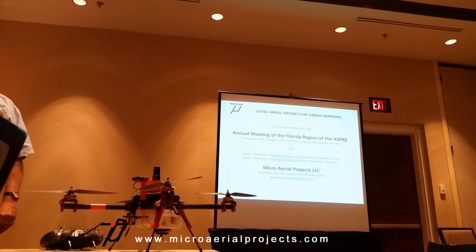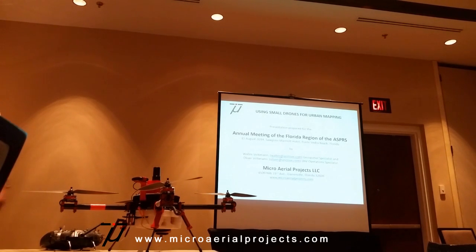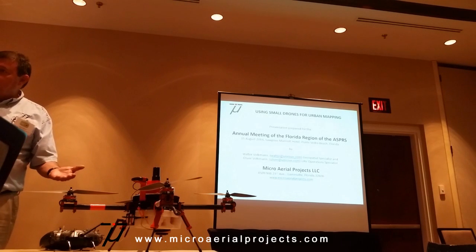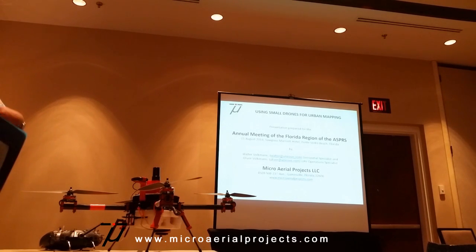What do you think the accuracy of the GPS is? This GPS receiver, you know, what was it quoted anyway? I mean, technically, it's a dual frequency GPS. It gives you generally, if your ambiguity is resolved, that means if you have resolved the integer number of waves between your antenna and the satellite, technically it's 5 millimeters absolutely plus 1 part per million of the range between your base and your rover. That's technically how GPS accuracy is defined in the geodetic sense.